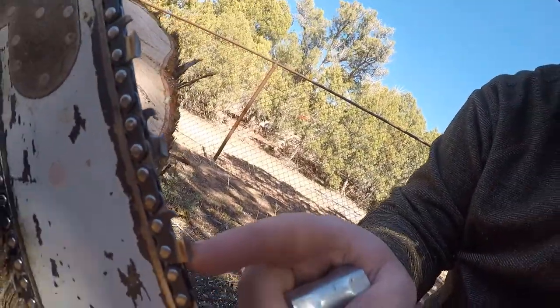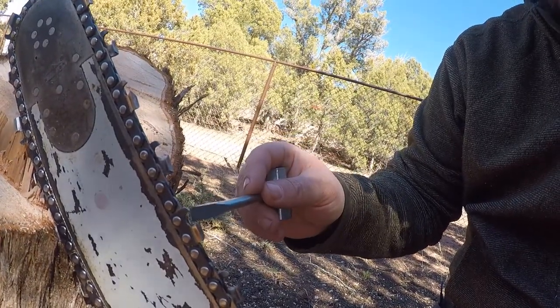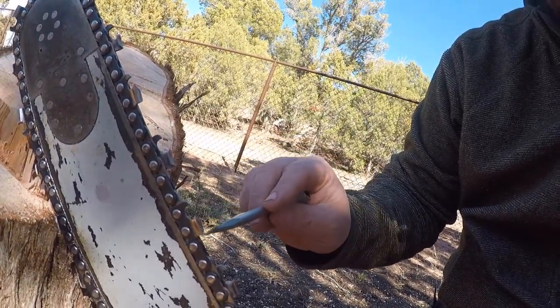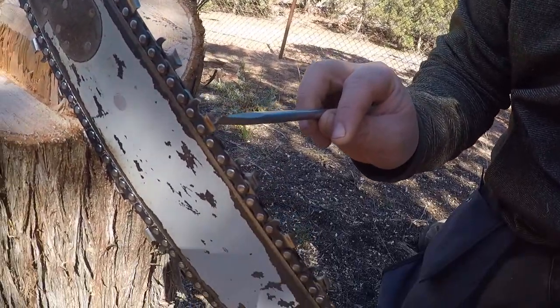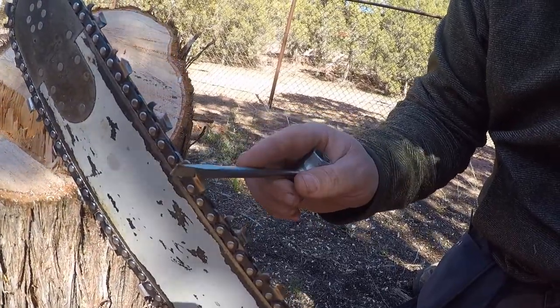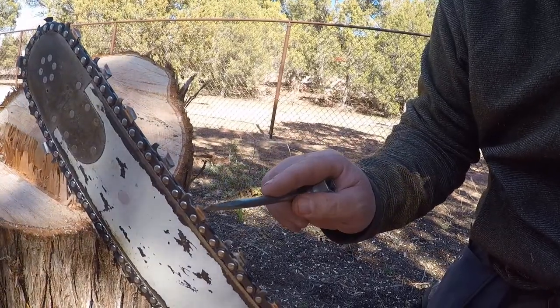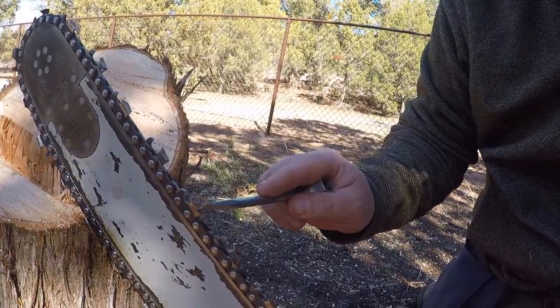At that time, if the chain has a lot of life left in it, you can look at a tooth of the chain. If the teeth aren't really short, you can see a little line on that chain. If it gets to that point, that chain's pretty much done. It also tells you the angle at which the tooth should be sharpened. But if your chain tooth is way back there, then it's time to get a new chain.